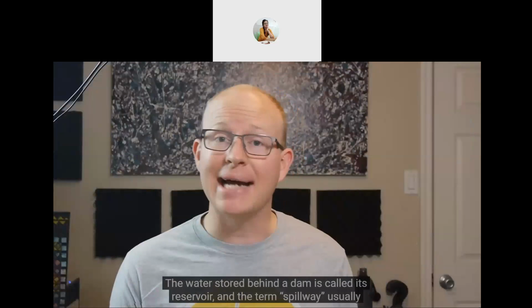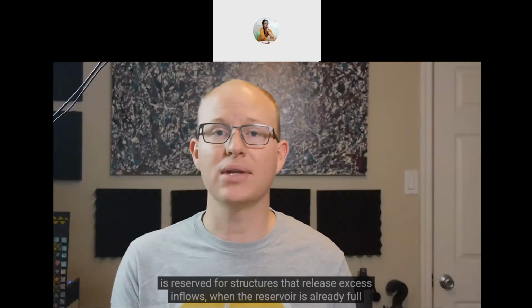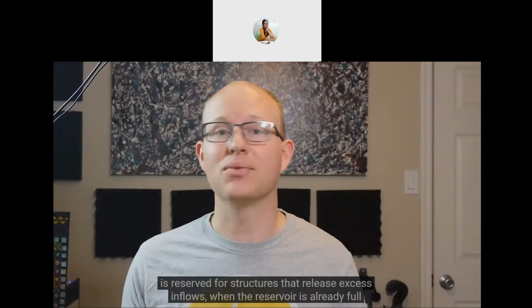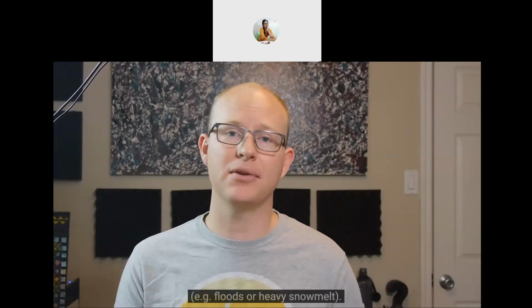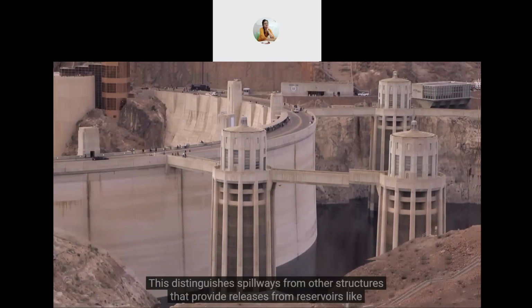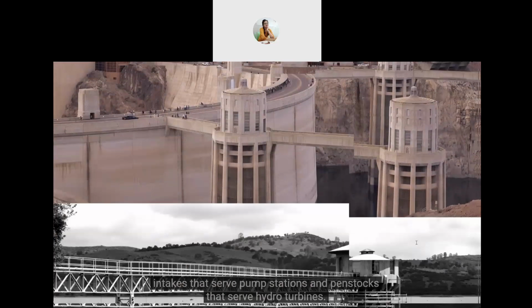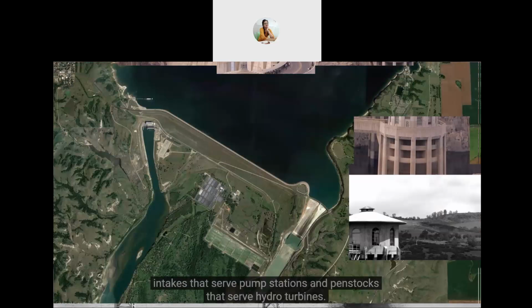The water stored behind a dam is called its reservoir, and the term spillway is usually reserved for a structure that releases excess inflows when the reservoir is already full. For example, a big flood or heavy snowmelt. This distinguishes spillways from other structures that provide releases from reservoirs like intakes that serve pump stations and penstocks that serve hydro turbines. Because of the variability in inflows, many large dams have two or more spillways.